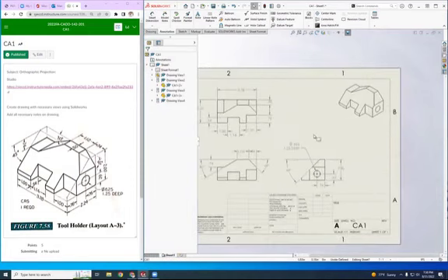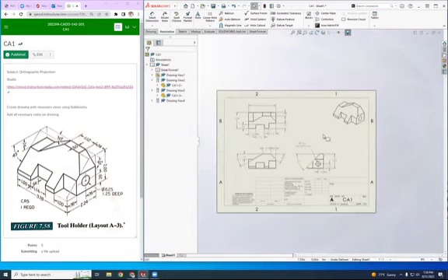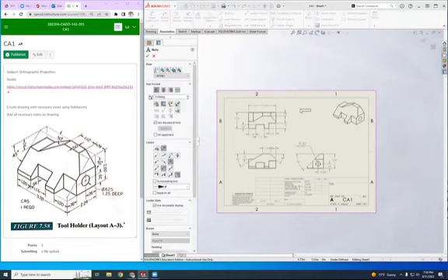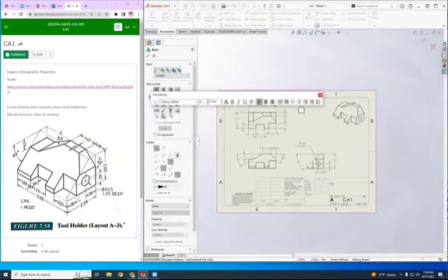So this is your orthographic projection drawing. Front view, top view, right side view, fully dimensioned with the dimensions given, your isometric view, and we're not done yet. Sorry. We have to add our notes. What are the notes? This right here. CRS means cold rolled steel. Notes.